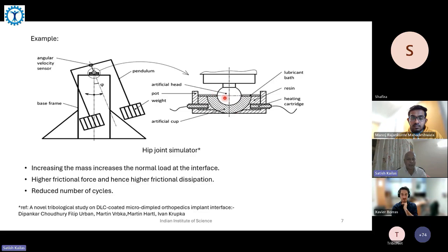And basically, what they studied was the effect of the roughness or different kinds of textures on the surface. So they put it on a machine like this, where you take this to a certain angle and release it. It will start damping, and the damping will be dependent mostly on the tribo contact. There's nothing else coming in apart from the air drag that is there.